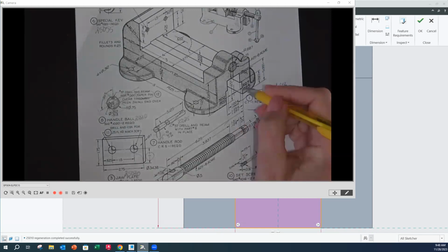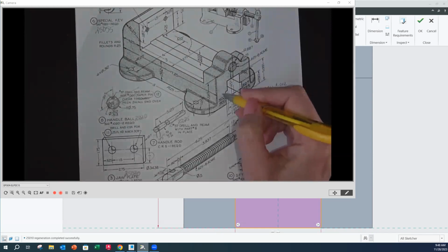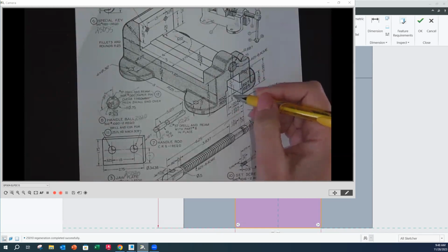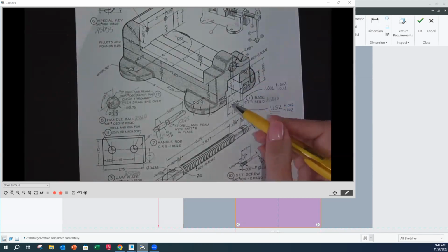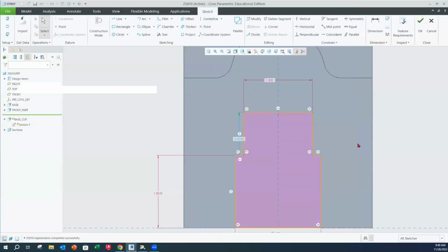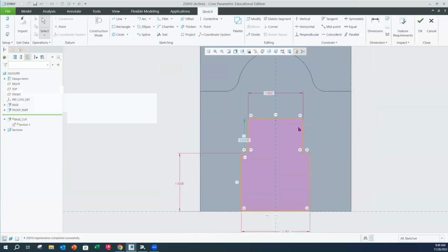Now, you don't need to worry about these 2 dimensions because it's going to automatically center, as long as you set it up correctly, for those 2 dimensions. So in my model here, notice that I don't have those side values at all. I just have my middle dimension here, and it's mirrored. So I drew the one side, and then I mirrored it over the center line.